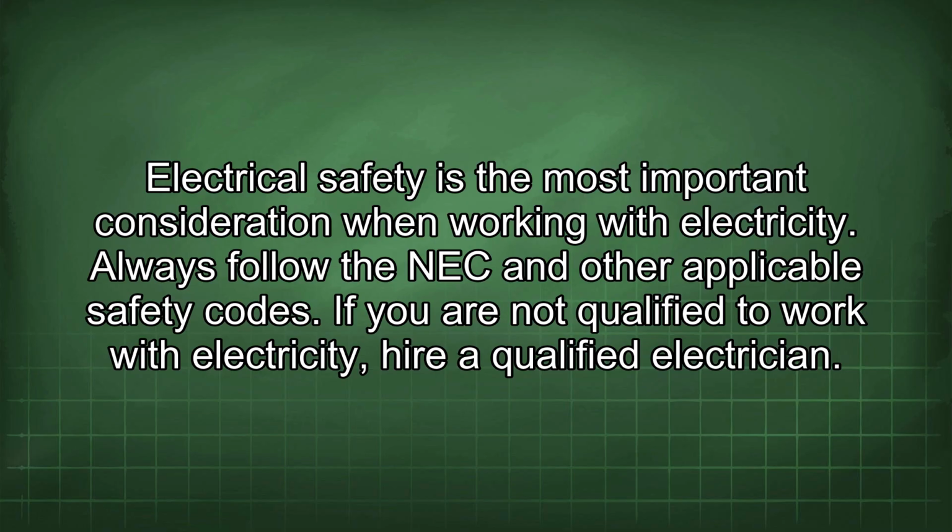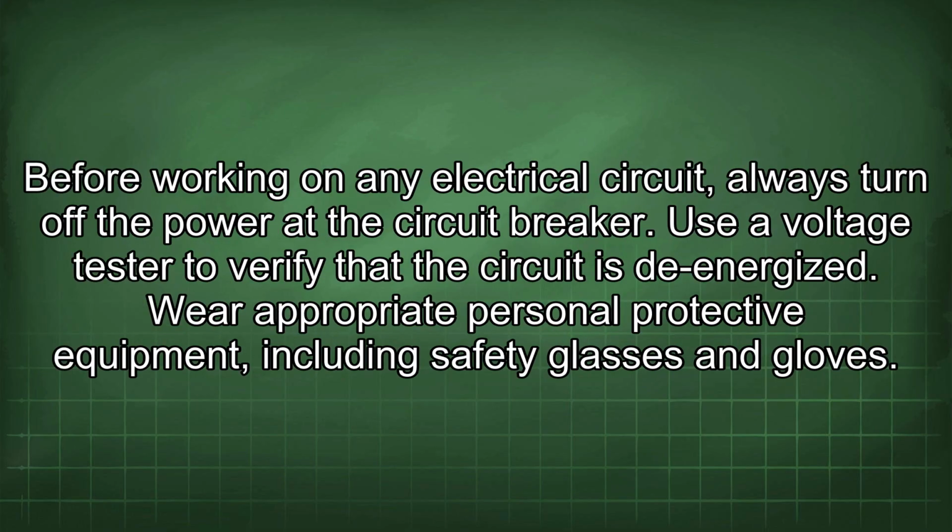Electrical safety is the most important consideration when working with electricity. Always follow the NEC and other applicable safety codes. If you are not qualified to work with electricity, hire a qualified electrician. Before working on any electrical circuit, always turn off the power at the circuit breaker. Use a voltage tester to verify that the circuit is de-energized.